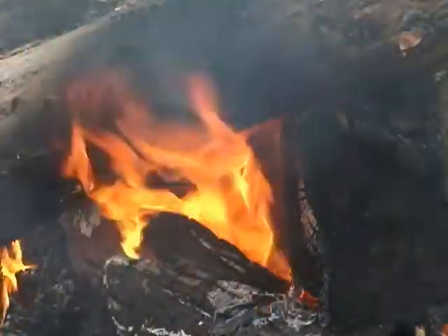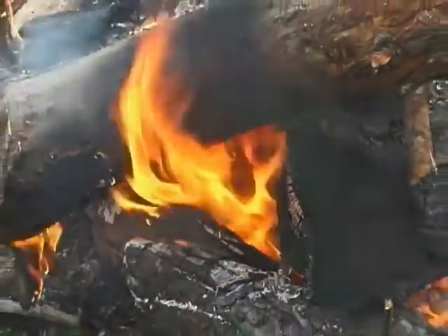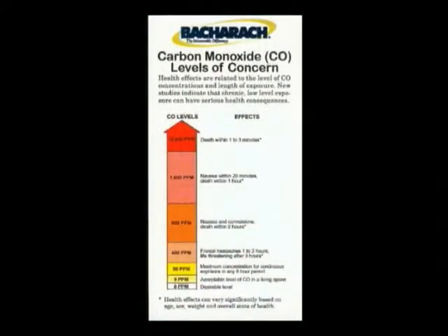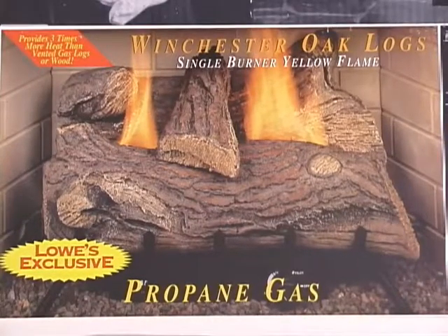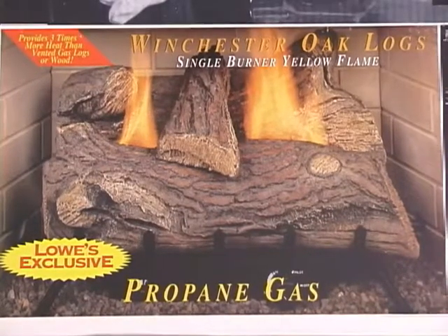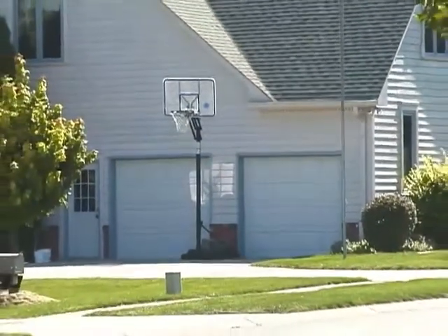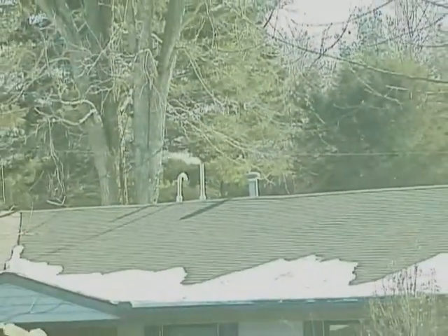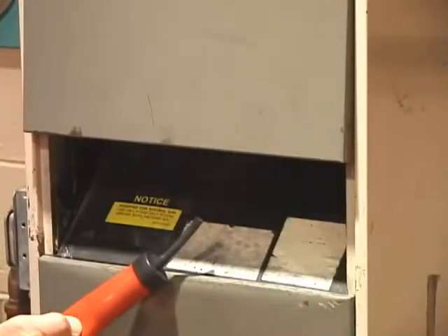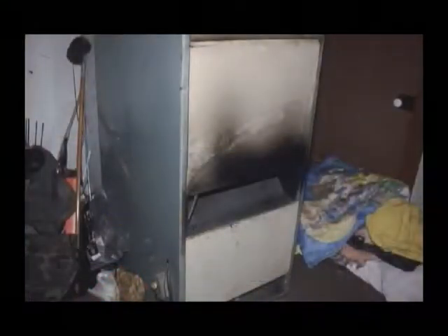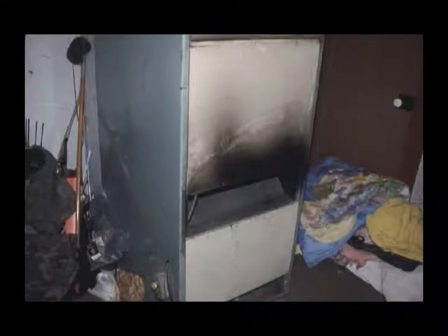In the previous two videos, we discussed the combustion process and the health effects of combustion byproducts, especially carbon monoxide. We discussed the many possible sources of carbon monoxide, including unvented combustion appliances, as well as other interior and exterior sources, such as attached garages. And we emphasized the importance of venting all byproducts of combustion out of the living space. When vented appliances such as furnaces, boilers, and water heaters don't vent properly, hazardous combustion byproducts, possibly including carbon monoxide, can enter the living space.